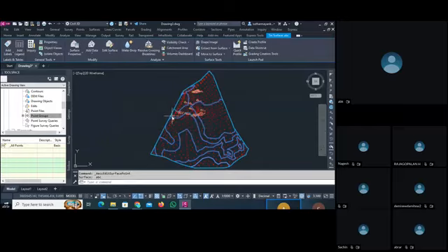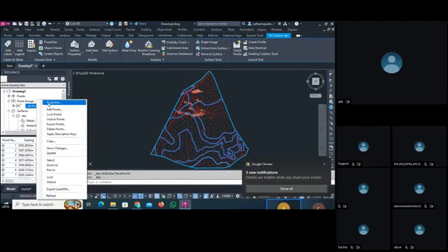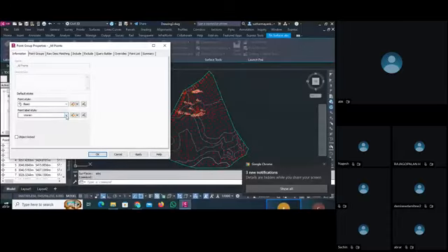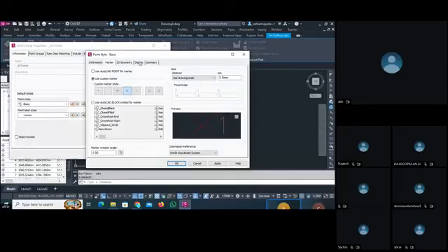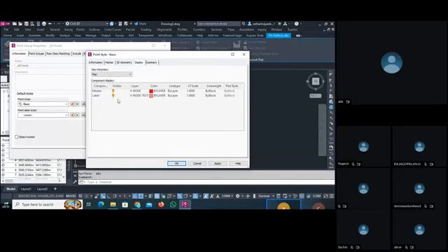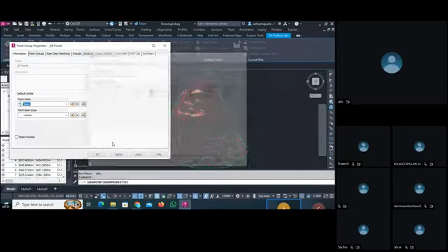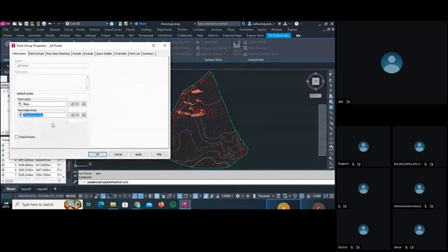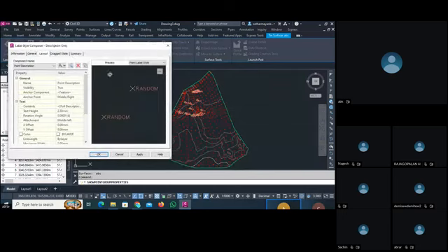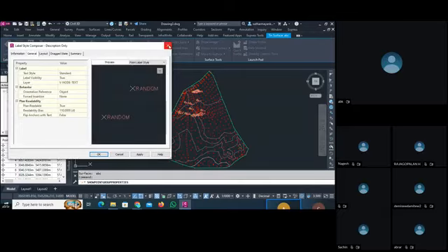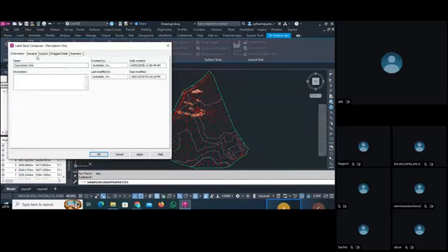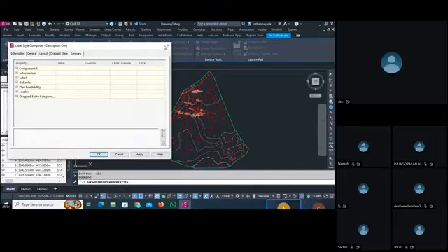So what it wants to say is, we select a surface style here. See, in the point group, I go into properties. We have the point style here. We can go into our point style, in the display option, our marker label is okay. Then we can go here, like in description only, and we again edit this in the drag style summary. Done. So all the things are created properly. Okay, that's okay.